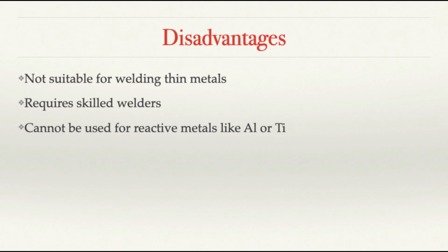Now one of the disadvantages is that arc welding produces a huge amount of ultraviolet rays as soon as the metal touches the electrode, which is very harmful if viewed by naked eyes. So it is always recommended to wear protective gear in front of your eyes so that you don't end up damaging your eyes.